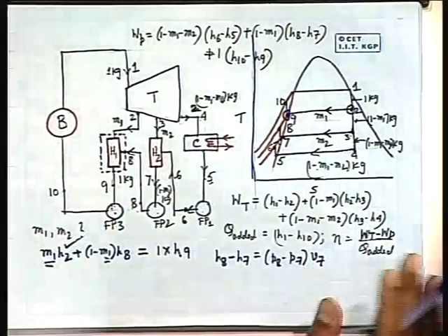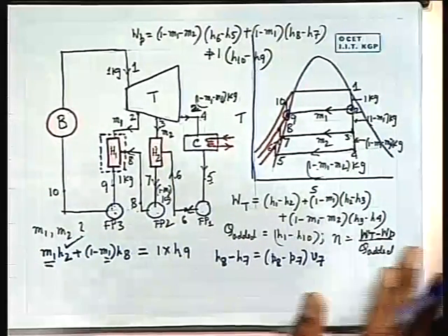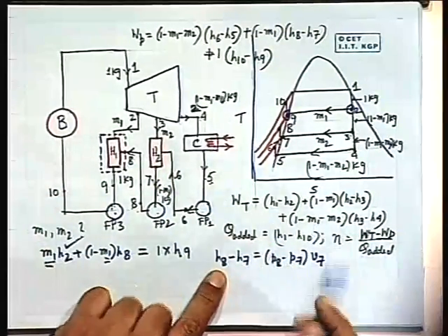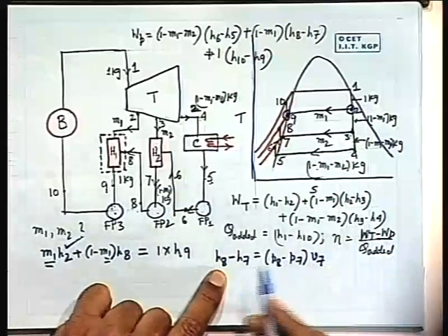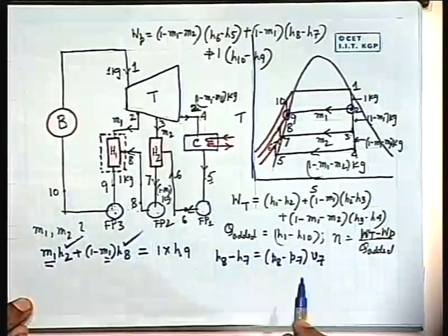put the value of enthalpy 0 at 0 degrees Celsius at any pressure, which means at any pressure, Cp into T is the specific enthalpy at temperature T. So that is another way of doing. This is also another way of doing, and these two are very close to each other. Your concept is the main thing. In calculation, there may be very little differences. So anyway, the thing is that we can find out H8.